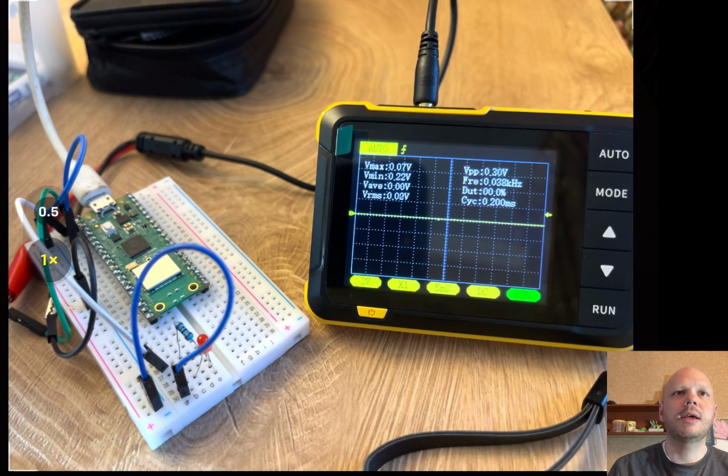I don't see on the screen, you see like it's getting brighter and then dimmer, brighter and then dimmer. All I see is on for 5%, off, on for 5%, off, on for 5%, off. And you can see exactly what that's doing with the duty cycle and the 20 milliseconds for the cycles.